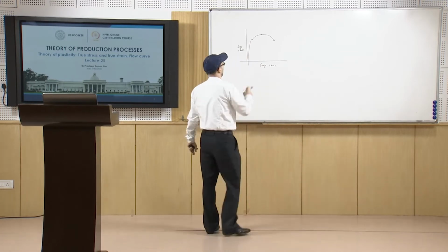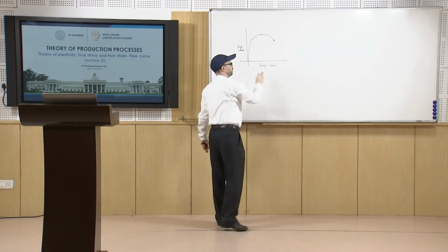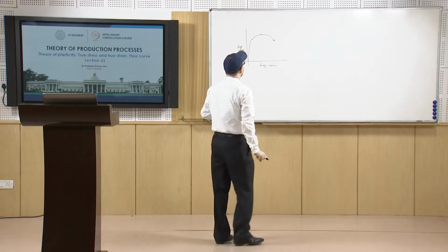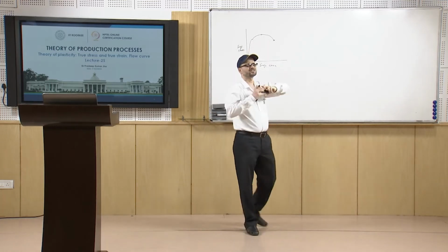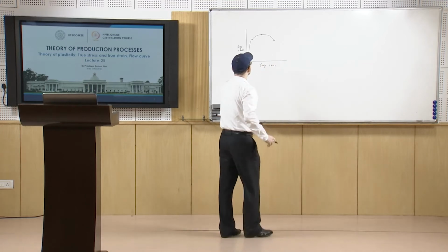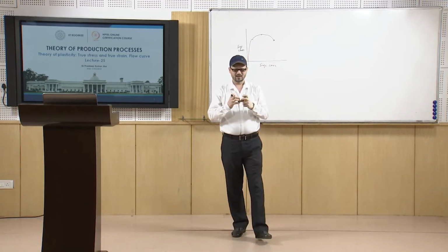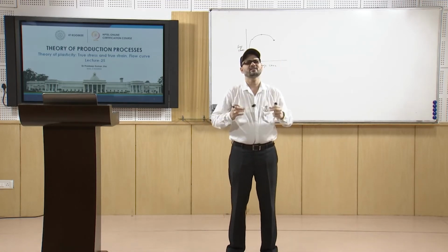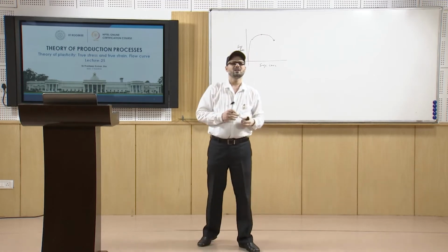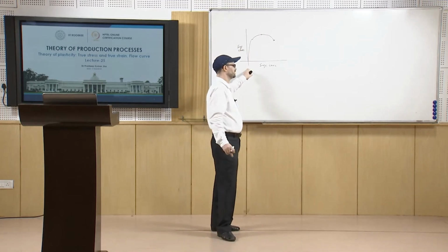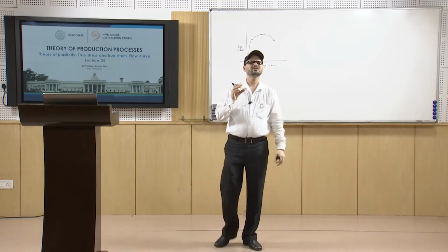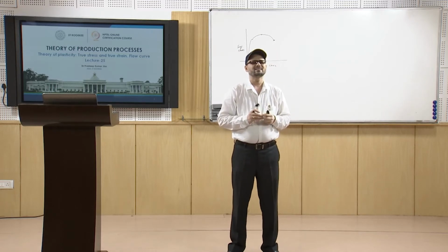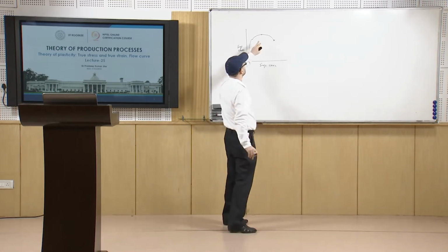So that is why after this point it will go on decreasing, because in actual, after this point there is considerable decrease in the cross section. Although whenever yielding starts, from that point itself there will be change in the dimensions of the specimen. Gauge length will be changing, cross section will be changing. Now that is not incorporated when we do the analysis based on the engineering stress strain curve. So basically what is done is that you have to do that consideration.